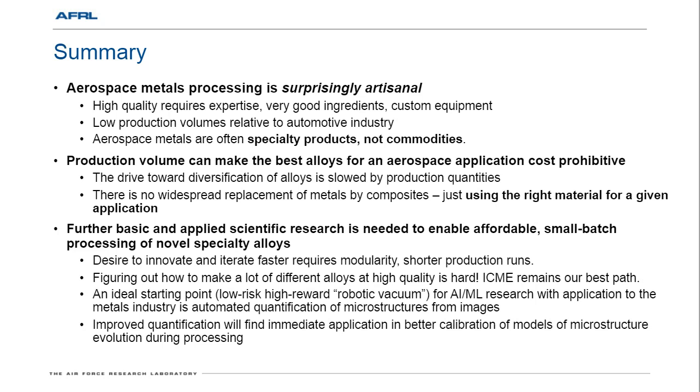In the case of titanium, we have to have high-quality reconstructions because we tend to look at the material in Ti-6-4. We're looking at the alpha phase, but when you're in alpha-beta processing, the beta phase texture evolution really matters for subsequent development of microstructure.